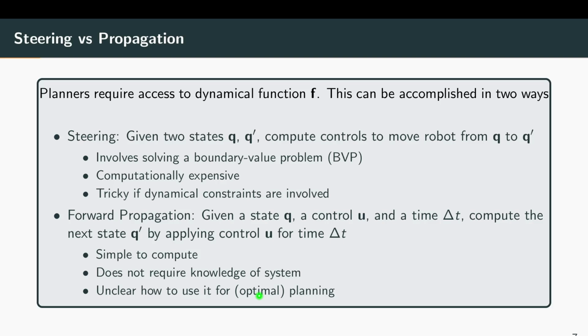And that by itself actually means we have to solve a kinodynamic motion planning problem. So it's kind of almost like a chicken and egg problem. Depending on the system, for simple systems, there's actually closed form solutions for this. For other systems, it's very tricky, and you use more numeric approaches or optimization.